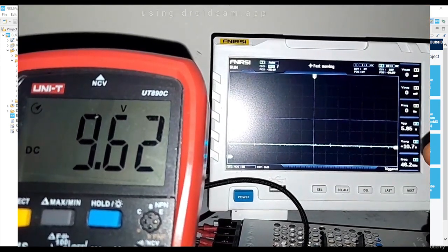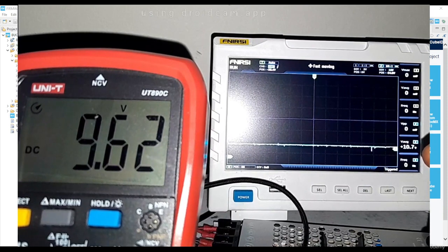And there we are. The voltage is about 9.62 volts, but it should be noted that the set point has been changed. The set point has been changed, and you can actually see that on the output. One thing specifically should be taken into account here, which is the fact that the resistor does change its resistance as a result of heat, i.e. the resistance actually goes up when it gets hotter, and that plays a role.